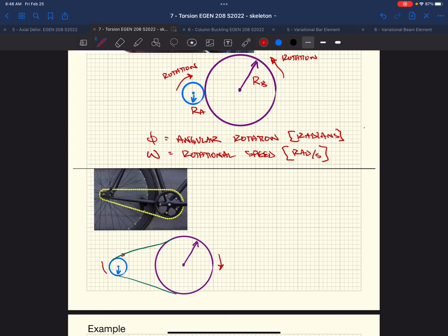Well, it changes the fact that now our rotation, right, if we had the radius of A and the radius at B, our rotation is in the same direction, right? And similarly, just like we had a gear assembly, if this gear moves 5 teeth, it essentially moves this chain 5 links to the right.